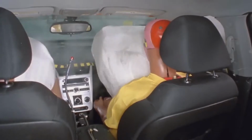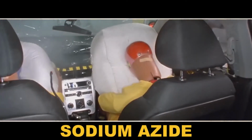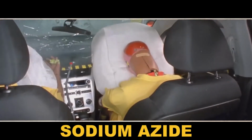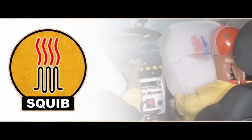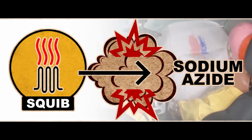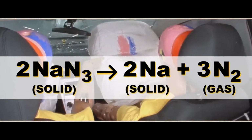Inside the airbag, there is a gas generator containing a mixture of sodium azide, potassium nitrate, and silicon oxide. When the car undergoes a head-on collision, a series of 3 chemical reactions inside the gas generator produce nitrogen gas to fill the airbag and convert sodium azide, which is highly toxic, to harmless glass.